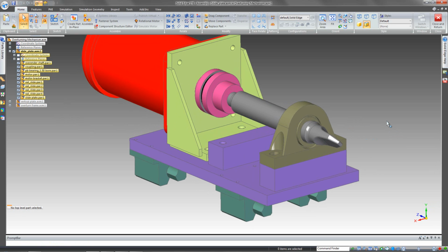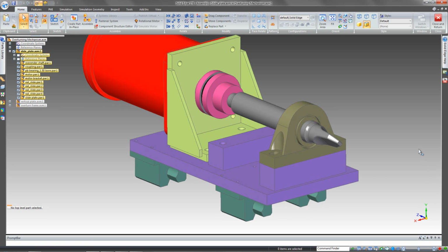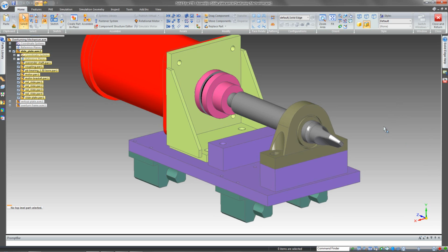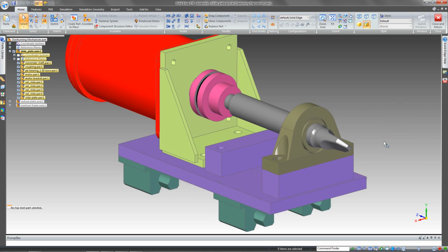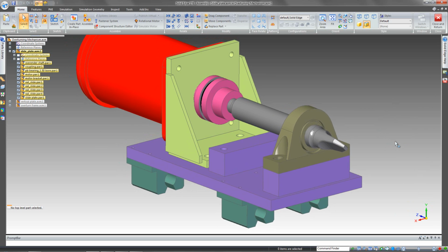And you will only see this option if the part is a synchronous part. If this purple plate here were a traditional part model with ordered features, even with face priority selected, it would highlight the entire part. So again, face selection will only work with synchronous parts.